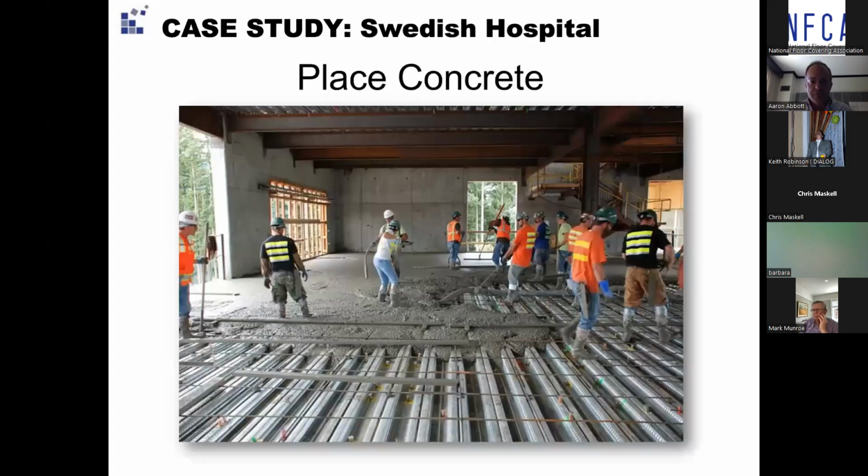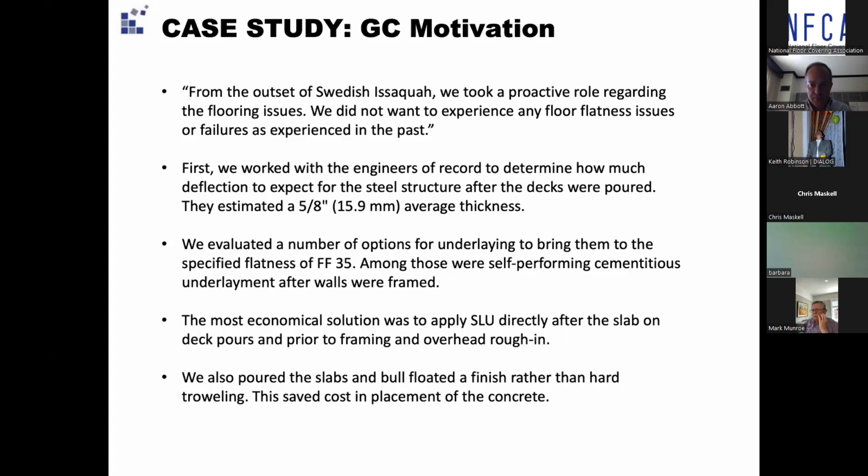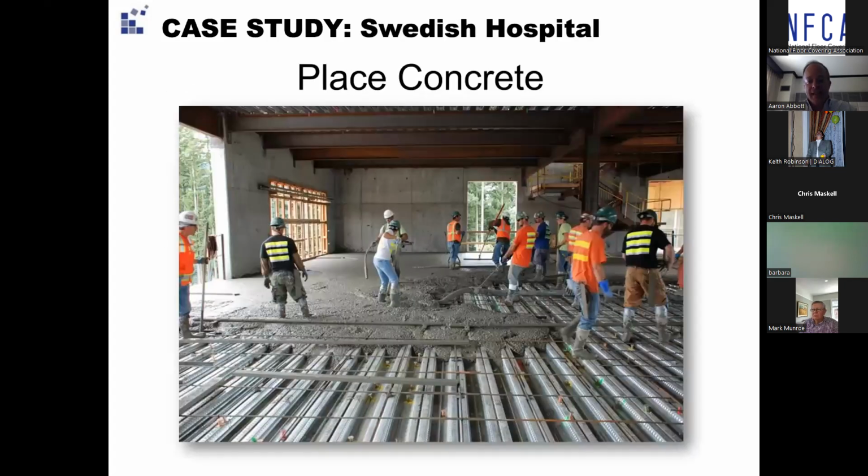I'll go through this. So again, Aaron, let me just back you up there for a minute, just to make clear, if they poured the base slabs and then they're going to immediately apply a topping, they still have to bring the base slabs up to dryness requirements and temperature requirements. So it's not just one after the other because time allows. You do have to have indoor environmental conditions that are conducive to getting that SLU poured according to its instructions, right? That's correct. Good point, Chris.